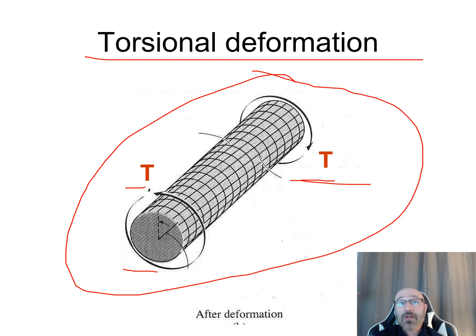And then we can go back to that grid sensitivity issue, which we've related back in course ME83 as well with SolidWorks, and talk about, as we do this mesh refinement, how does that affect our accuracy if we're looking at FEA of something like this, based upon the information of how we find how that deformation propagates through this with the length.